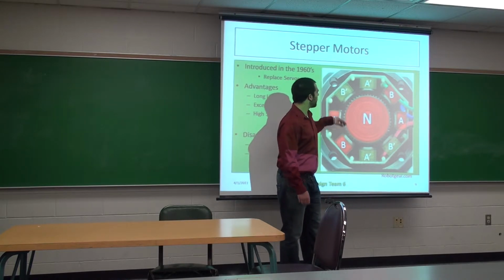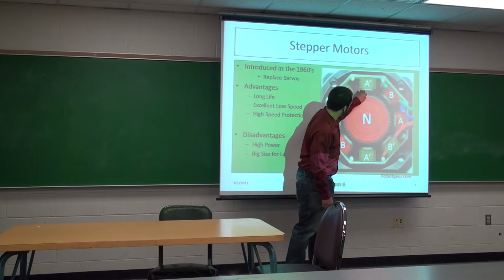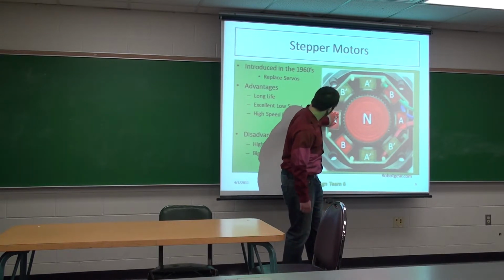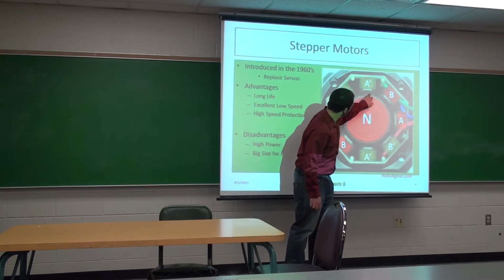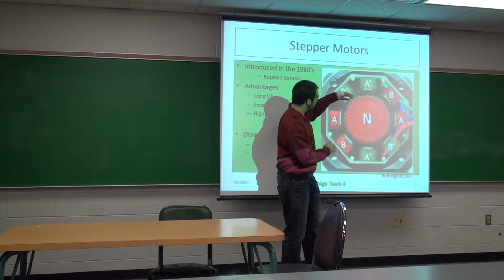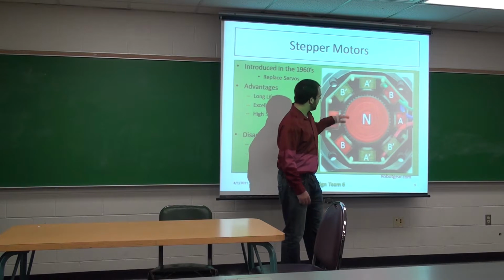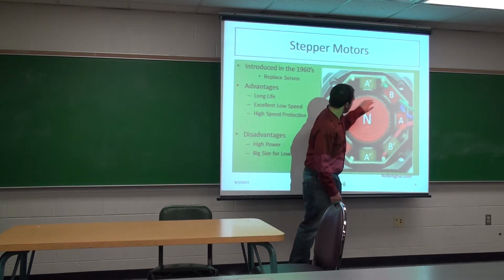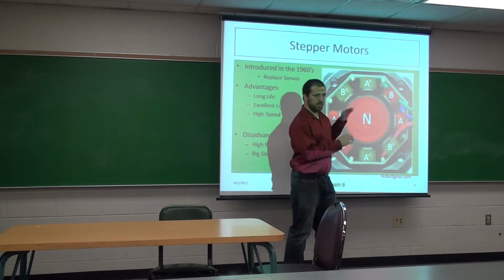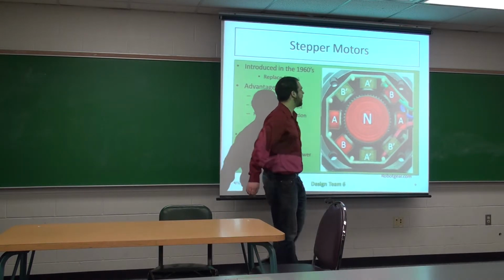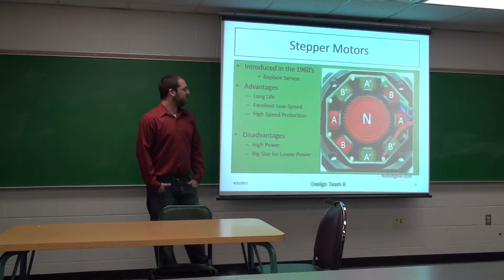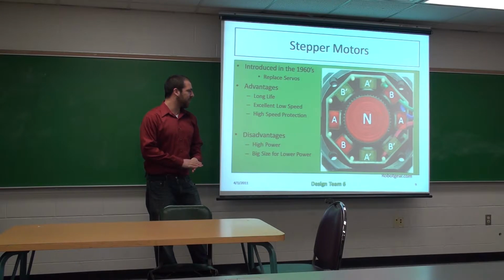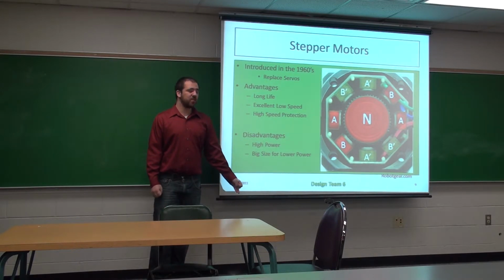180 degrees. So what this does is when there's teeth right here and teeth right here, when you turn phase A on, they're going to want to attract to the opposite, so teeth are going to line up right here, and you're going to have perfect alignment here, misalignment here. And then when you turn this off and turn B on, you're going to move one full step, and that's one whole tooth going to the next tooth. So in this application, it'd be 1.8 degrees, and this allows for not necessarily smooth movements, but very precise movements.